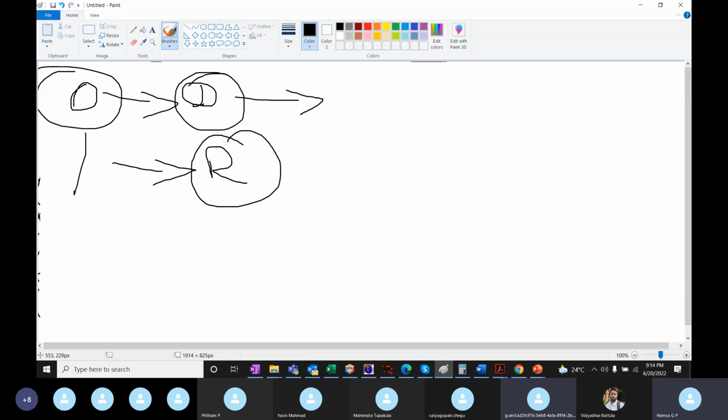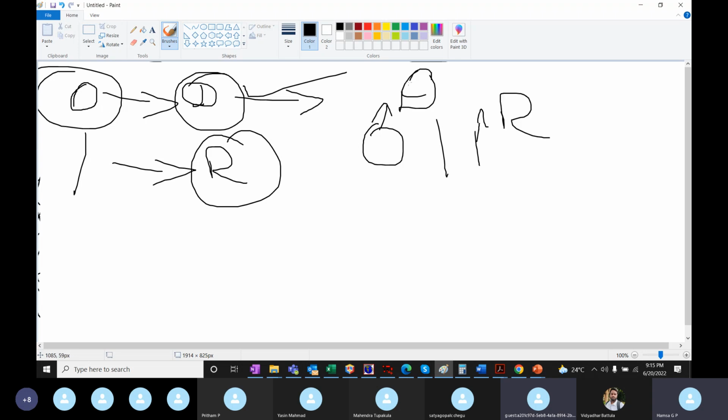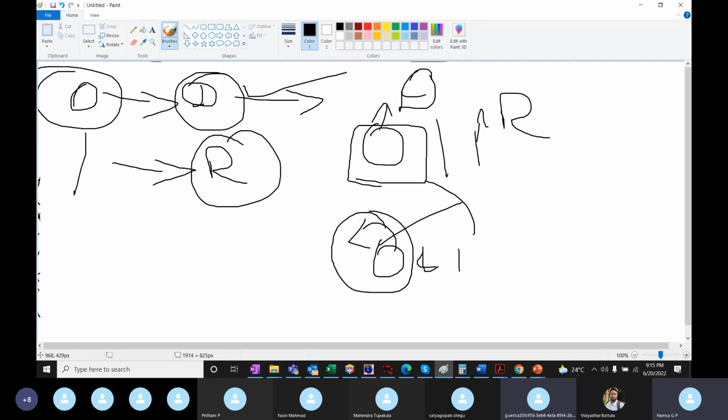What does domination or dominant mean? More powerful, controlling, a bigger value. It's powerful, correct? So assume there is a 0 and there is a 1, which are dominant and recessive. Whom do you think is powerful here? 0. Very good. So assume 0 and 1 are transmitted at the same time. Who wins the fight? 0, because it is dominant.